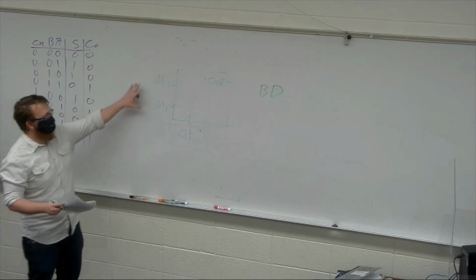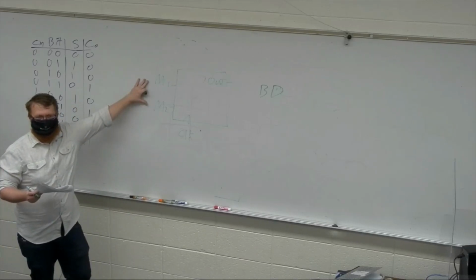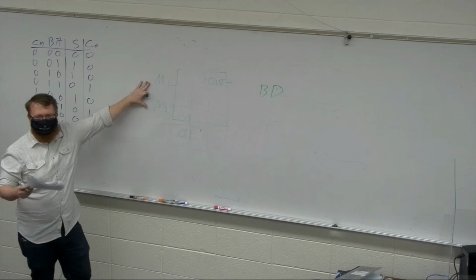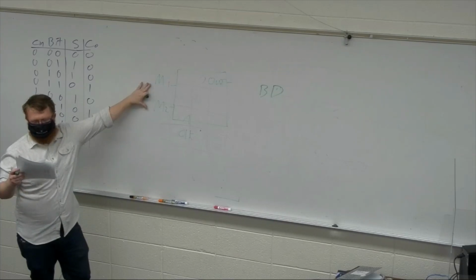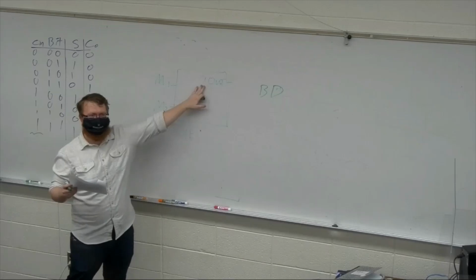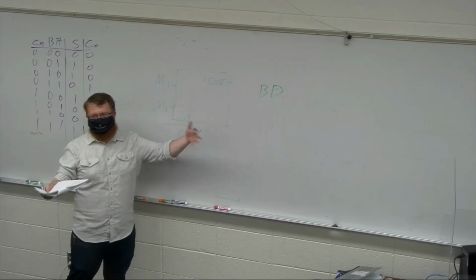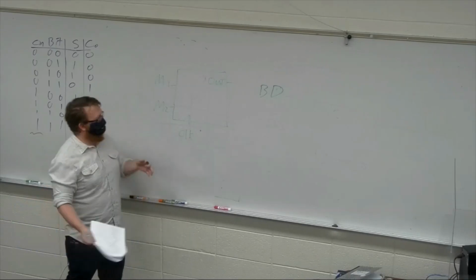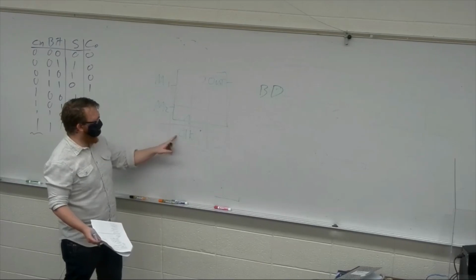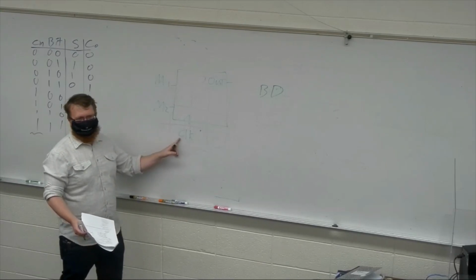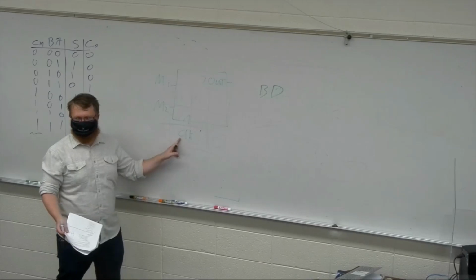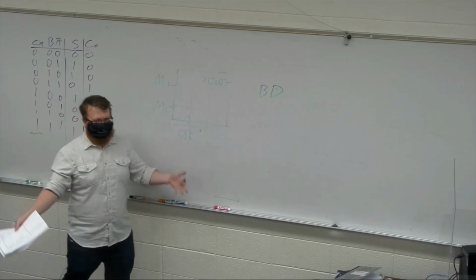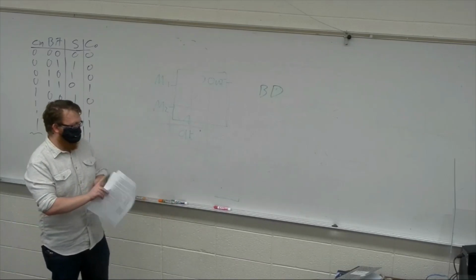And then it was just a matter of looking at what the logic was doing, and you could have quickly drawn out a truth table for M1 and M0 versus out. And then you would have hopefully seen pretty quickly that it was the same truth table as a JK flip-flop. I saw a couple of muxes and a couple of ROMs. The weird ones were muxes, which don't even have clocks. Muxes aren't clock devices. Well, you can put a clock through a mux, but it's not a clock device. So that was that one.